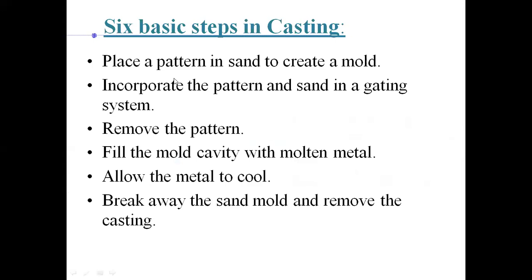So that's the first step: placing the pattern in sand to create a mold. And we'll see a video also that will clarify these steps. You place that pattern in the sand to create a mold, incorporate the pattern and sand in a gating system. The gating system will also be made, and then you remove the pattern.